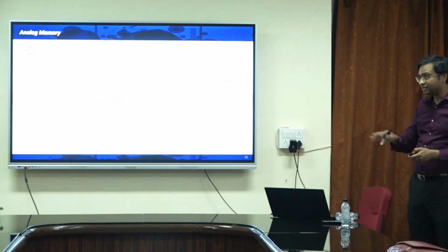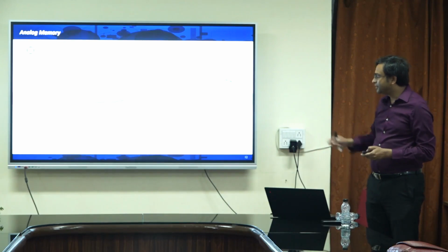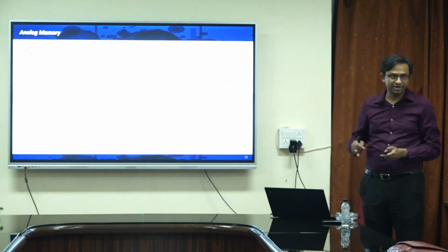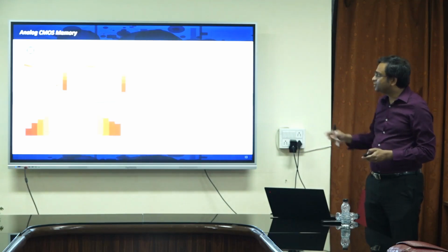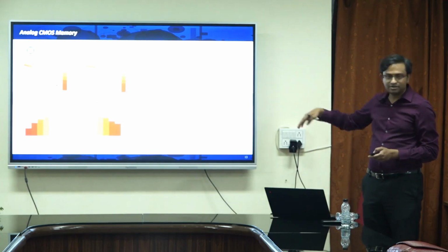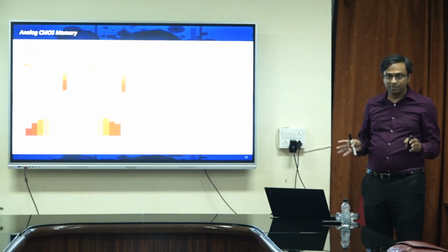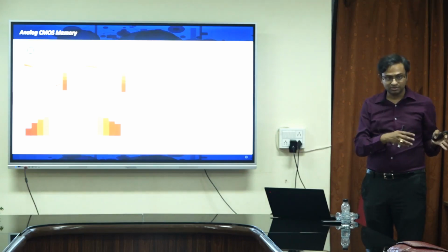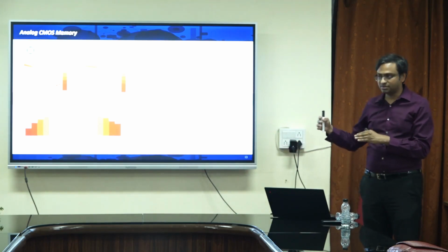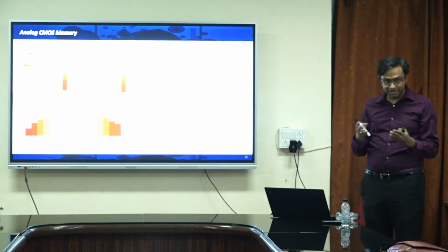I think this is not as relevant given the diverse background of this group. But we do a lot of other studies on these memory devices just to benchmark them against other memory technologies. Okay, and then you can actually use an N-type transistor or a P-type transistor. You can do it with CMOS capability, because at the end of the day, what I was talking about is in-memory compute, because the silicon technology is CMOS, right? And your memory technology is completely different, right? Based on NAND flash or NOR flash devices, we are trying to merge them together for in-memory compute.